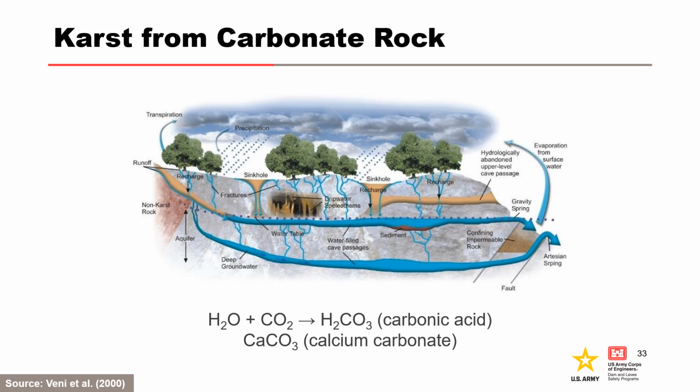Structure is important for karst development, and karst is opportunistic. Water flows along pre-existing cracks, faults, joints, bedding planes, etc. And dissolution is normally worse near the surface. As water works deeper, its calcite concentration goes up and it becomes less aggressive.